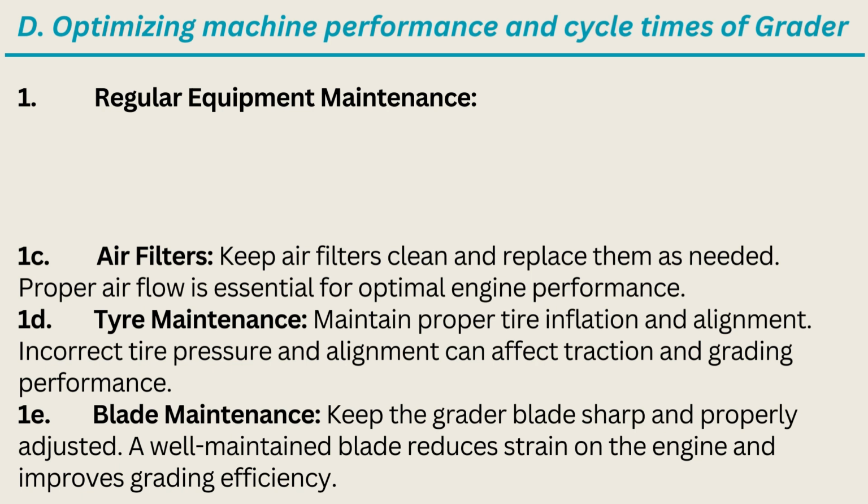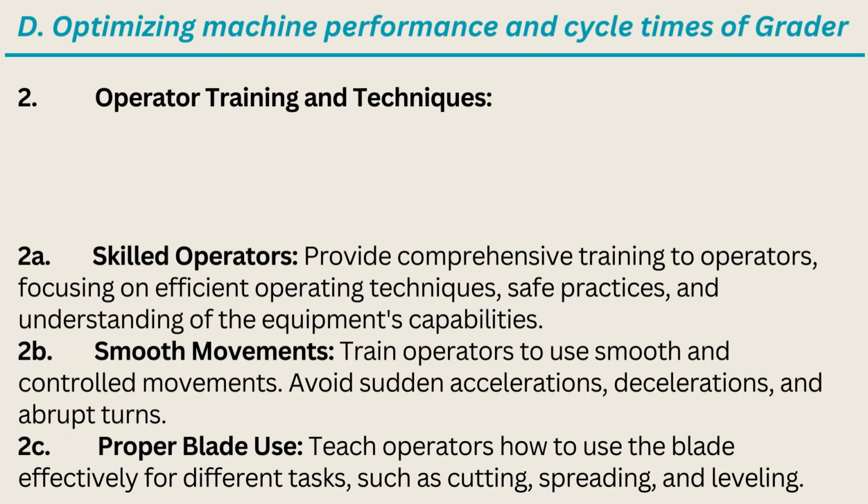1D. Tire maintenance. Maintain proper tire inflation and alignment. Incorrect tire pressure and alignment can affect traction and grading performance. 1E. Blade maintenance. Keep the grader blade sharp and properly adjusted. A well-maintained blade reduces strain on the engine and improves grading efficiency. 2. Operator training and techniques. 2A.